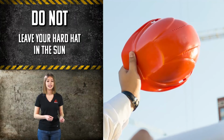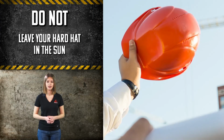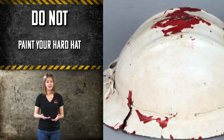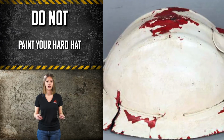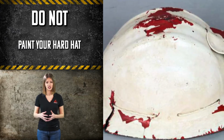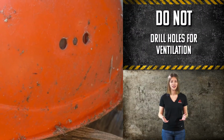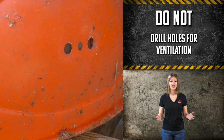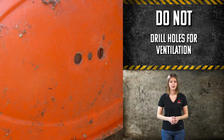To help keep your hard hat in good condition, you should avoid the following. Leaving your hard hat in the sun, as plastic and fiberglass can be damaged by the UV rays. Painting your hard hat. The chemicals in paint can change the hat's ability to protect against electrical conductivity and/or weaken the shell. Using harsh cleaners or solvents on the hard hat. Drilling holes for ventilation. Drilling holes into a hard hat could weaken the shell. If you need a vented hard hat, please speak with your supervisor.